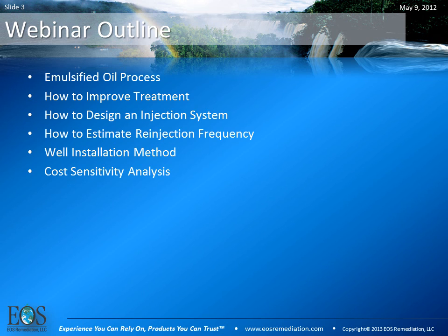I'm going to be looking at how to improve treatment, how to design an injection system, how to estimate reinjection frequency, basically looking at a variety of different well installation methods, and then we'll look at cost sensitivity analysis. This is not the order in which I'll be doing it. Basically these parameters are sort of intertwined, and so I'll be discussing all of these, but I will touch upon them all just in a different order.